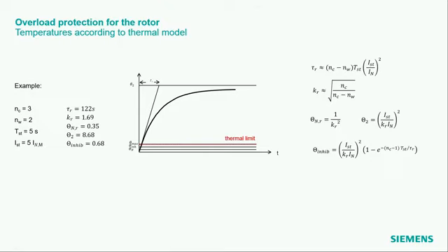Here we have 1/3, and this is somehow clear if I think about I have 3 starts from cold and 2 from warm, so the difference is 1. And if we say, okay, approximately we get the same temperature rise for each start, then it's 1/3, and this is basically more or less 1/3. It's not exactly 1/3 because I have a bend here in the curve. The curve becomes flatter even here at the beginning, and this is this 1% difference here.